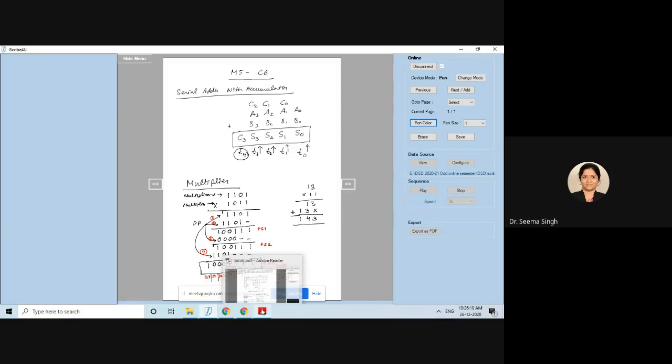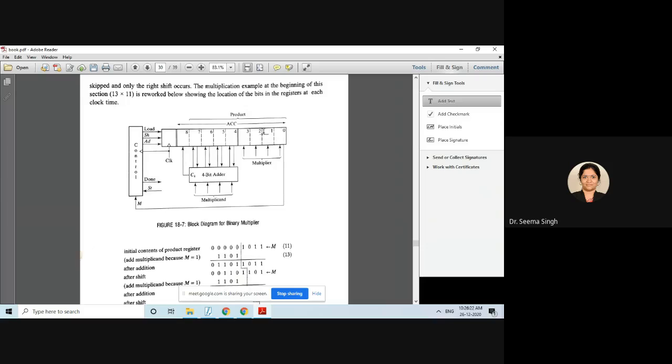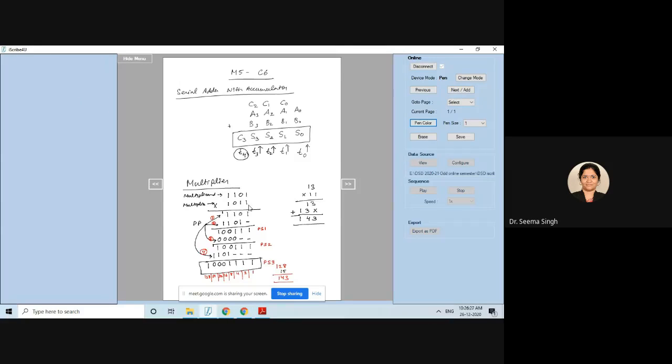Now you will understand with this, your multiplier is kept here. Multiplier was your second number, and multiplicand is your 1101. So your 1101 only is being added again and again, because multiplication is repeated addition. You can see your partial product number 1, 2 and 4 was the same number as the multiplicand.